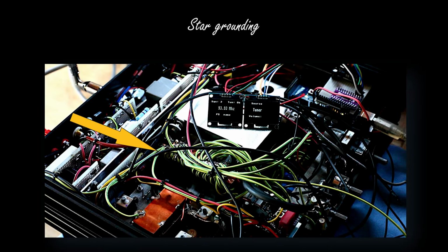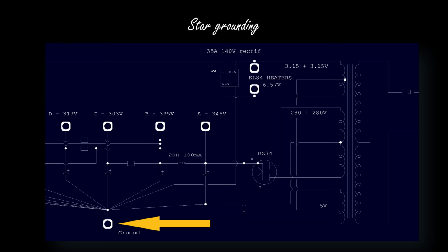You will need to experiment a little bit, but again, if you adopt the extreme solution, for sure you will not hear hum. Even the ground side of the power supply capacitors should be connected to the same grounding point, with the exception of the first capacitor.